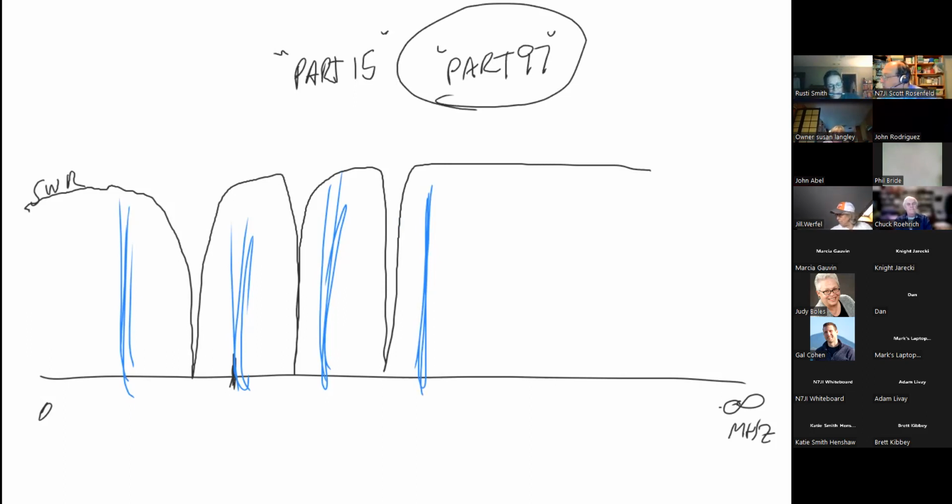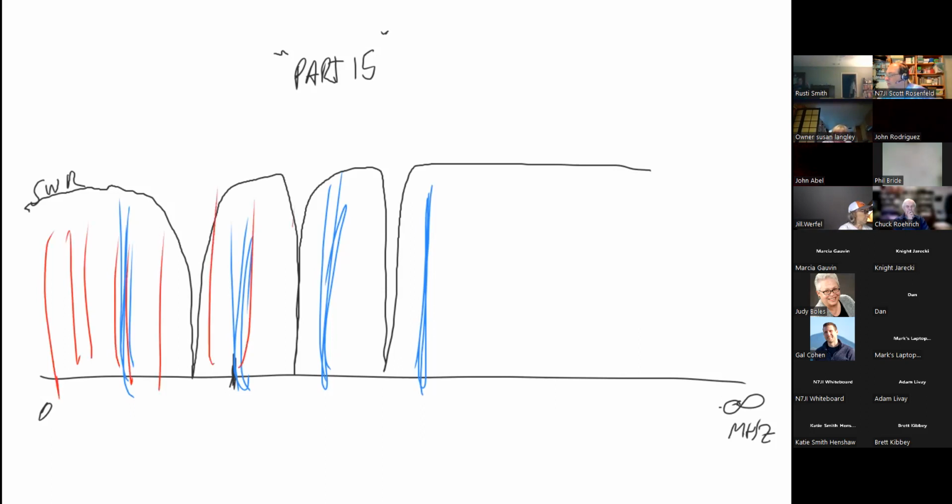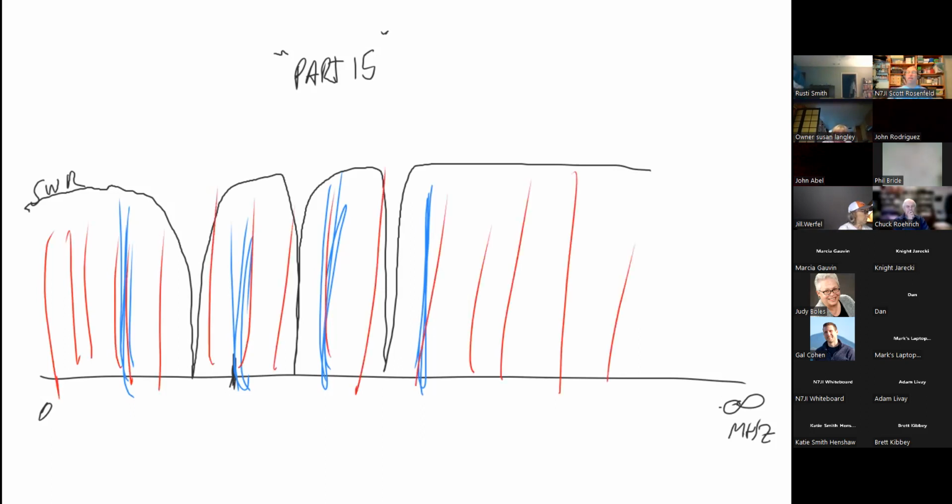Part 15, if you look at everything else in your house, your cell phone, your power supply, a battery pack, everything will say this is a Part 15 device. A Part 15 device is an unlicensed, very low power transmitter of energy that also has to accept all forms of interference from everything else in the world. Because it's so low power, a Part 15 device can actually transmit everywhere, and give me a complete test of everything that I'm doing.